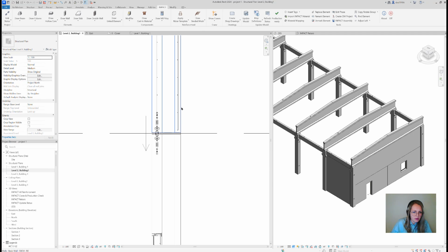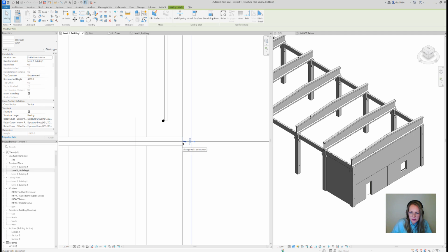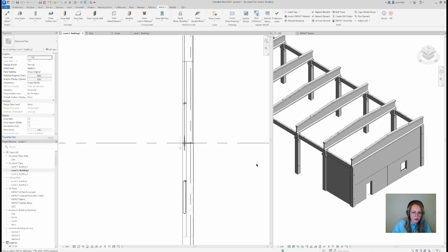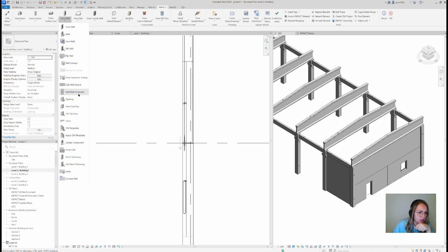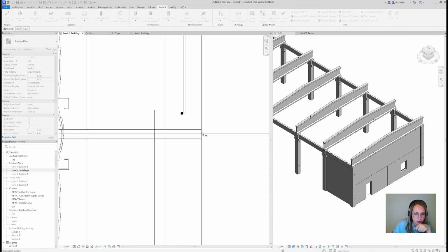We need to split the wall, and here it is, right? If I do it like this, I am going to split the wall, and afterwards I'm going to draw in these walls with the help of joints. That's the tool I want to show you. So first, split the wall, it must be vertically. Select the wall, it must be the one in here.